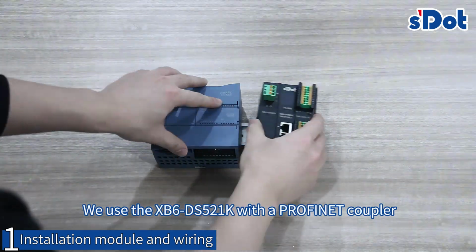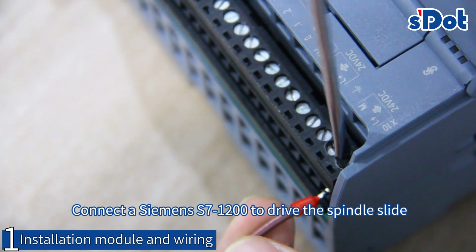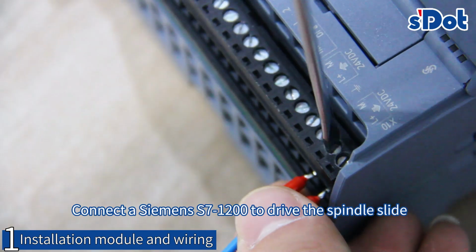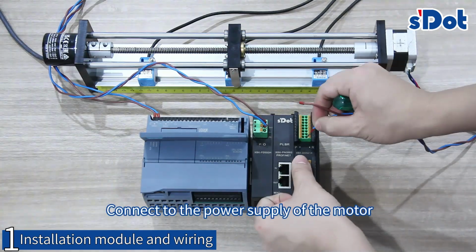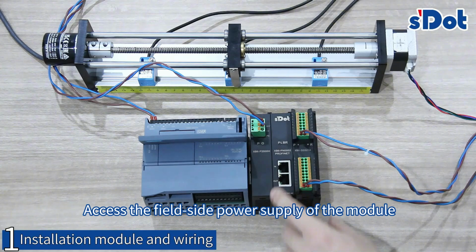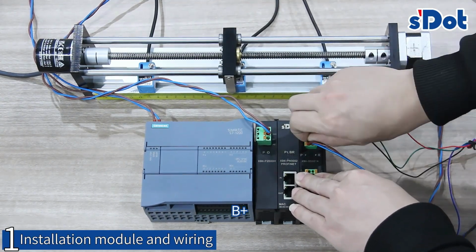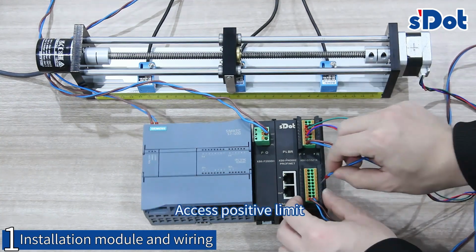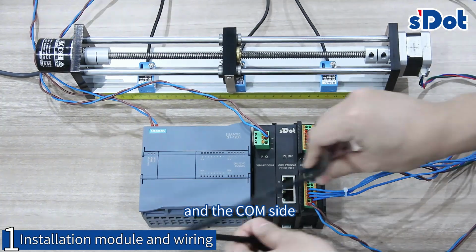Below, we use the XB6-DS521K with a Profinet coupler, connected to a Siemens S7-1200 to drive the spindle slide. Connect the power supply of the motor. Access the field side power supply of the module, and plug in motor positive pole A, negative pole A, positive pole B, negative pole B. Access positive limit, negative limit, origin, and the COM side.